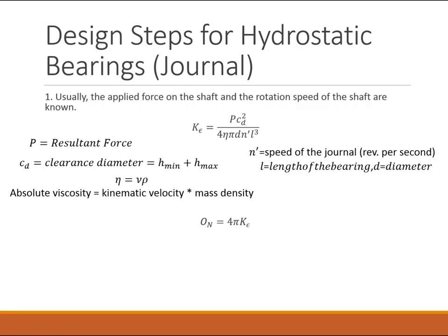All of those will help me know this dimensionless parameter, this K epsilon. Once I know that, I'm going to find an Ocvirk number, and the Ocvirk number is a function of this K that we just found. And from that I can get the average pressure.